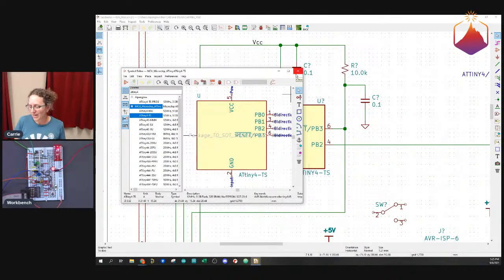But I'm picky and I didn't like it. So I will sometimes do a mix of symbol representation and physical representation, because when you're troubleshooting, it is very handy to have some idea of the physical layout of a part by looking at the schematic. And because this is a relatively simple circuit board with so few parts on it, it doesn't add a whole ton of confusion to also make that part look somewhat like it does in real life, for some things.